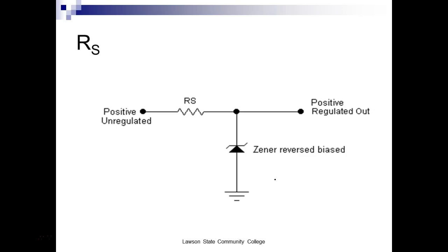I don't think these do, even though they should. So this power supply says it puts out 20 volts at 3.25 amps. And it doesn't tell you percent regulation, but I guarantee you that's basically an average, right? You understand? It could be pretty close on this one because it probably represents almost the same load all the time,